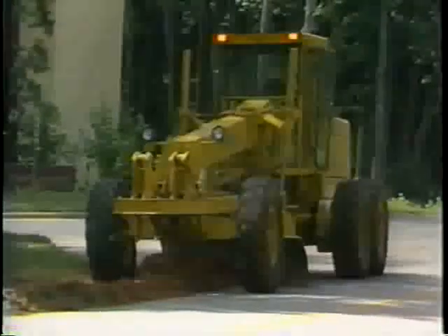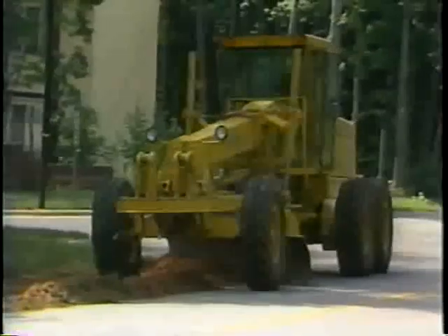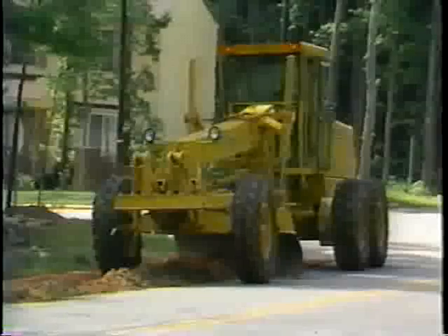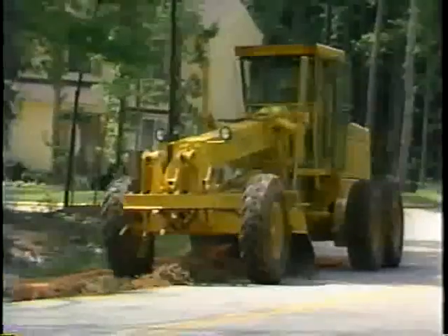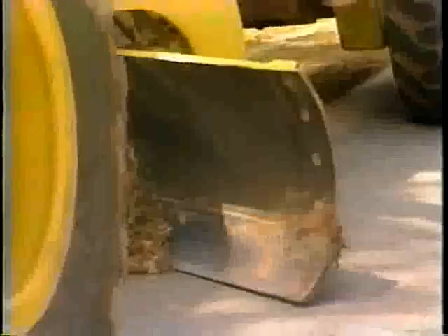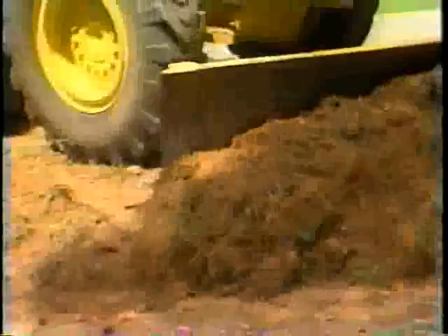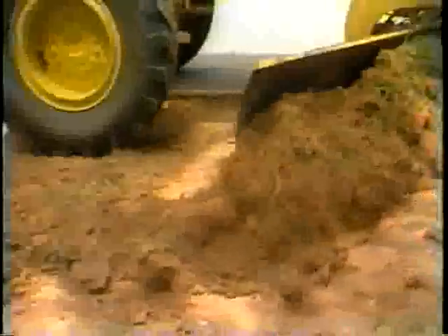On the second pass, pick up the windrowed material and spread it back across the shoulder. Again, a 45-degree angle is used for the blade. The toe of the blade rests at the edge of the pavement. The heel is at the edge of the shoulder. Set the blade height at the desired slope for the shoulder, typically 3/4 inch per foot.